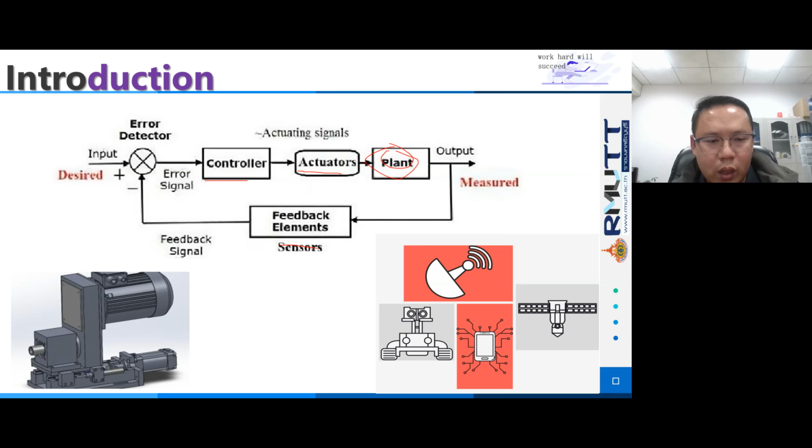Next, I will briefly explain how the system works. A desired rotational state, like position, or velocity, or torque, is set as the set point. The system measures the current rotation state using the sensor. Errors are calculated. These errors are used to determine how much the control signal needs to be adjusted.